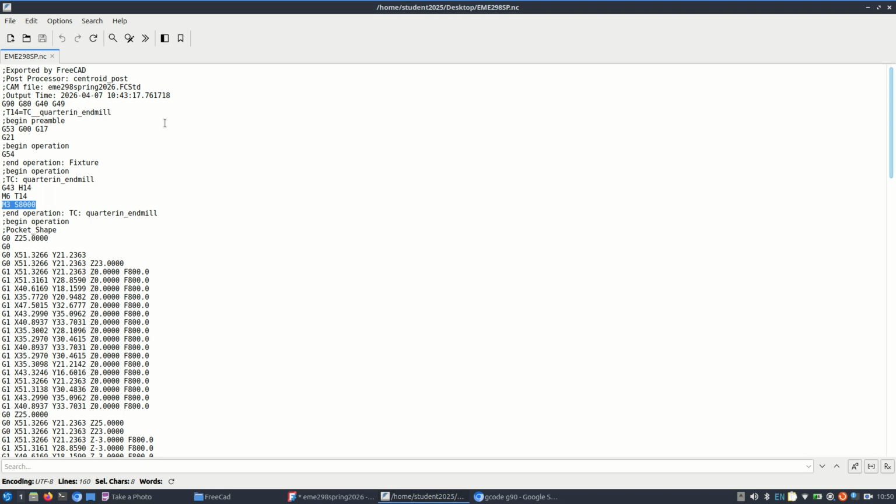down to the position. I don't think that's very positive. I would rather go back to the first position there, and then go down, and then do the work again, right? So we could change X, Y because we wouldn't be cutting there. Yeah. We could change Z. So see, we can always go in, and let's say it's taking long and I just have to do the last pass of this thing again. You just go and manually delete stuff. Sometimes it's just easier to go ahead and edit the G-code right there.